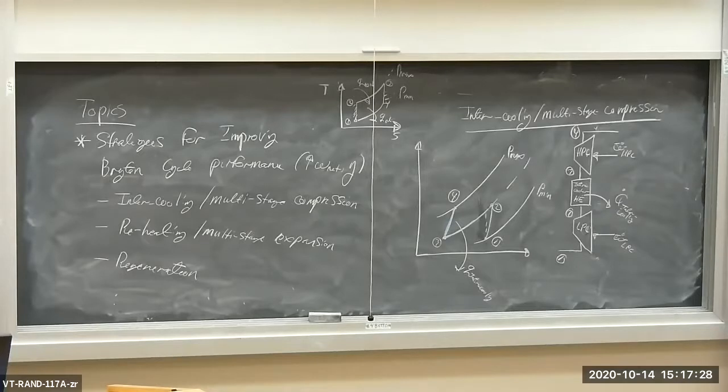You have a gasoline or a diesel engine and you pre-compress the air before it even goes into the combustion chamber, and you do it with a turbine, a turbocharger. Once the air gets compressed in the turbocharger, it gets cooled down by a heat exchanger placed in front of the radiator on your car, and that heat exchanger is called an intercooler.